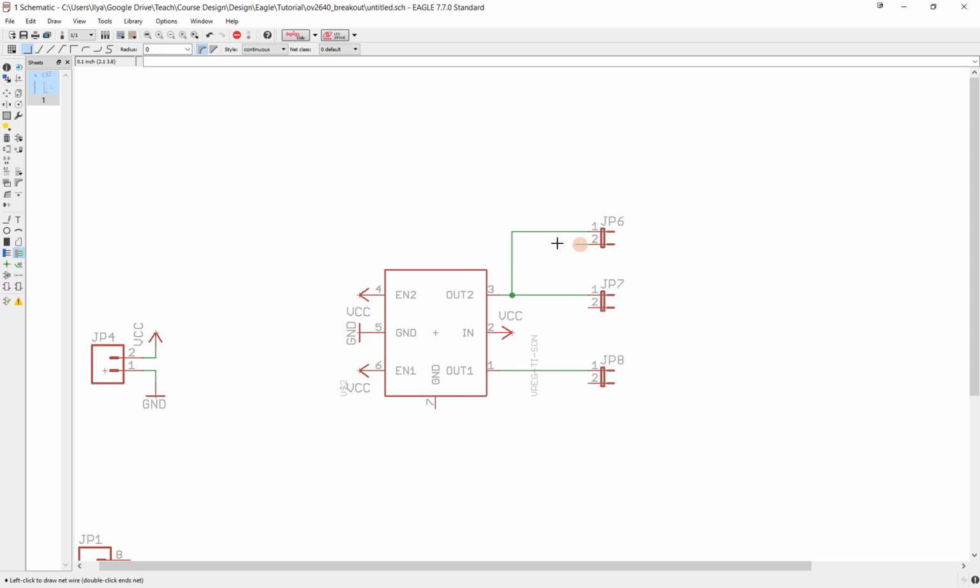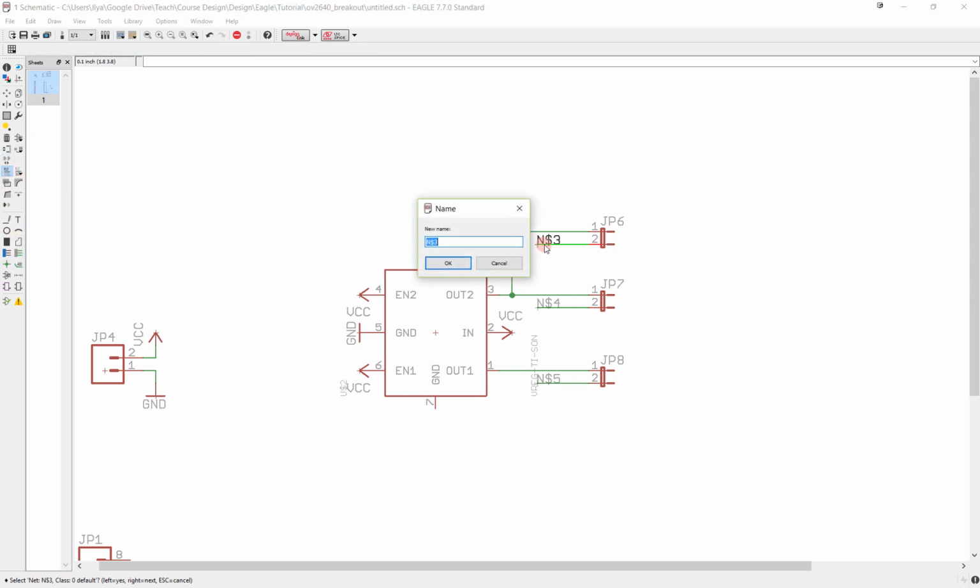And so then, to actually show what these outputs are going to be here, and to make these nets proper, if I connect these jumpers, that is, if I just short them together, that's what a jumper will allow you to do, either short or disconnect. If I short them, then these lines right here are going to be the actual power supply. So let me label them. And so first I'll place these labels, and then I'll title them. So you can see for now they're just generic names. But then I name them, and this is going to be my DOVDD. This will be AVDD. And this will be DVDD.